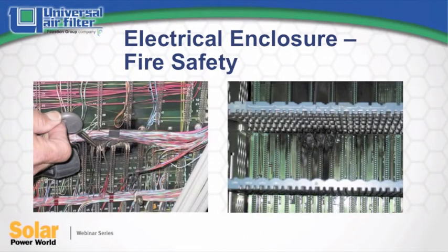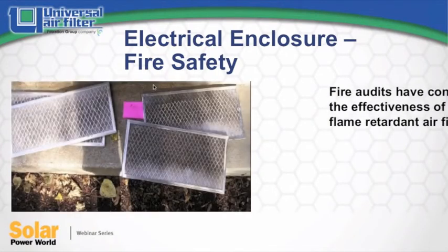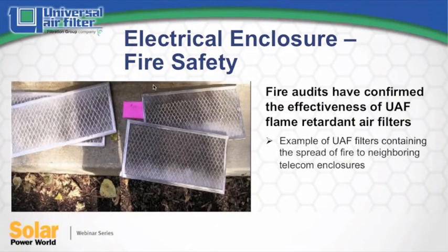Be sure to use only flame retardant plastics in your chassis, and make sure that they meet the highest UL flame safety ratings that are available. As you can see in these photos, the polymers used in these chassis are self-extinguishing and do not promote the spread of flames. Air filters also need to be UL 94 compliant to contain fire spread and keep systems reliable when subjected to catastrophic conditions.